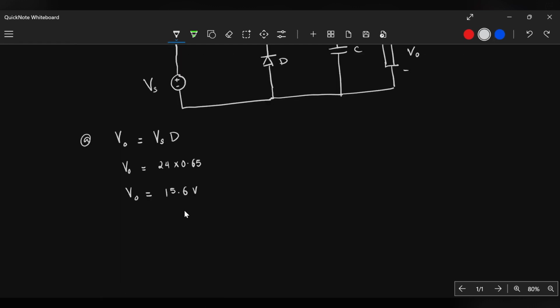So for the buck converter, part B, the Imin is given by this formula. Imin is simply equal to the output voltage multiplied by 1 over resistance, minus, not plus, minus (1 minus duty cycle) over 2 times inductance, times the switching period. Remember that period is simply 1 over frequency, so we can substitute that since we're given the frequency in the problem.